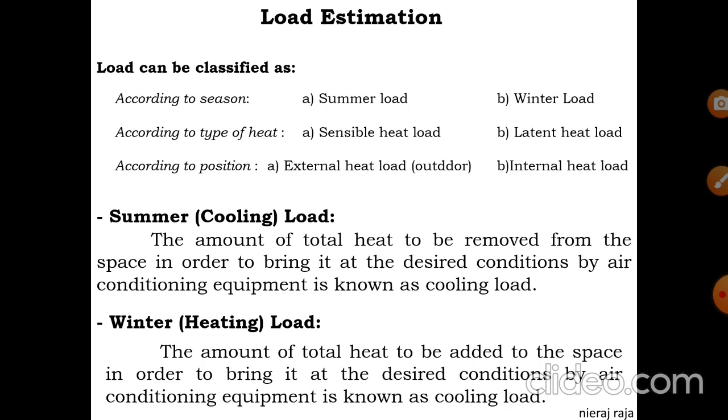Again, depending upon the type of heat you are going to focus on, which is under study, that is the sensible heat load and the latent heat load. Sensible heat load deals with your temperature, DBT: how much heat is encountered, how much DBT has changed. And the second one is the latent heat load, which deals with the moisture, that is WBT.